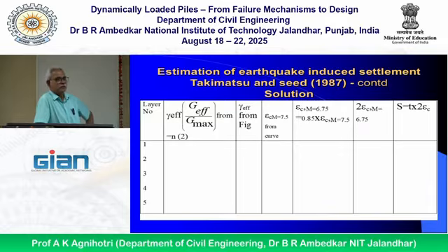Then it will become corresponding to earthquake of magnitude 6.75. Then Pike et al. recommendation to consider multidirectional effect, we will double the value. So this epsilon C will be multiplied by 2. Then settlement will be thickness multiplied by this value. Okay. So total settlement, if you have considered all the layers, then you will add up all, that will be total settlement.